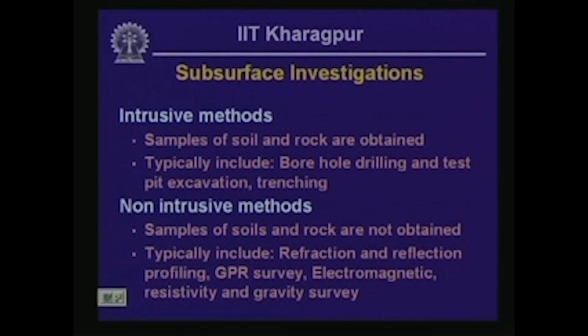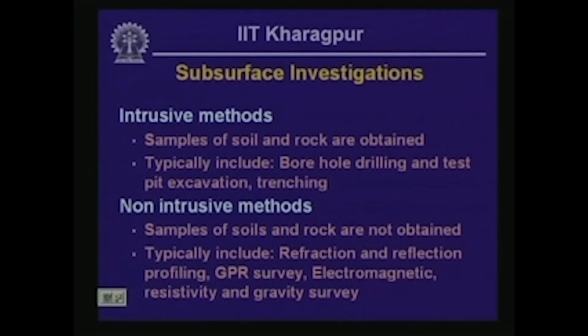Then we have to also carry out subsurface investigation to get more precise information about the elevation and the topography of the different stratigraphic units that are not visible at the ground surface. And also in this activity samples of different types of geologic units are obtained for subsequent laboratory testing.